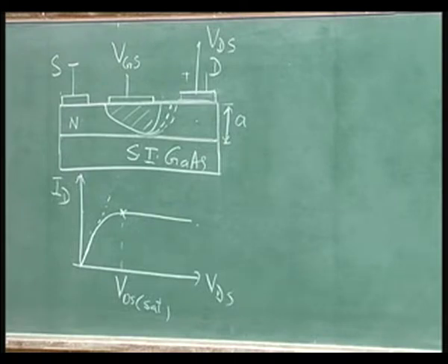This is the expression that we get, and look at that Vd sat. We have substituted Vp0 plus VGS minus Vbi. I substituted from this equation for this here, that is Vp0 plus VGS minus Vbi, and I have retained other terms as they are. Now, one thing that we have defined at this point is a threshold voltage.